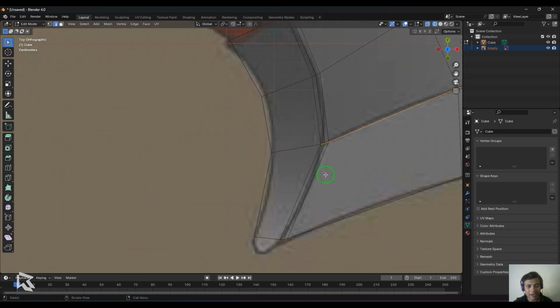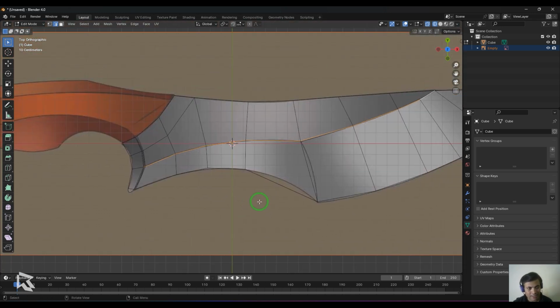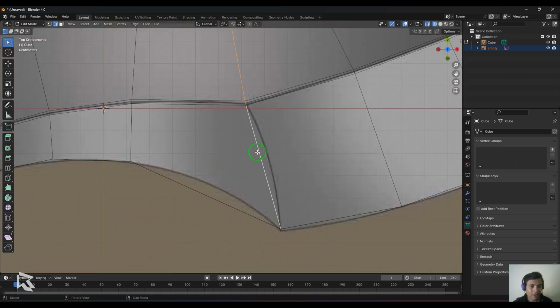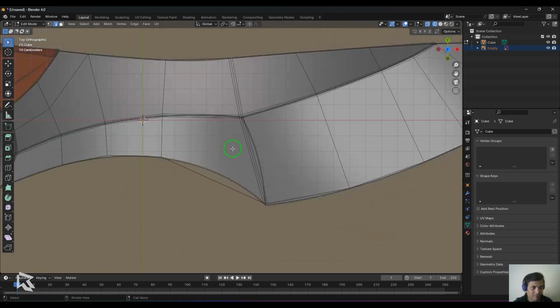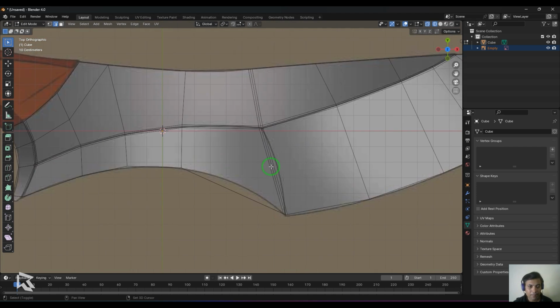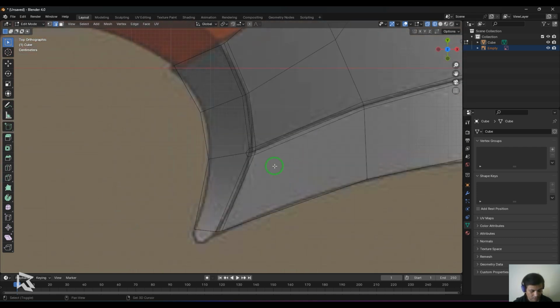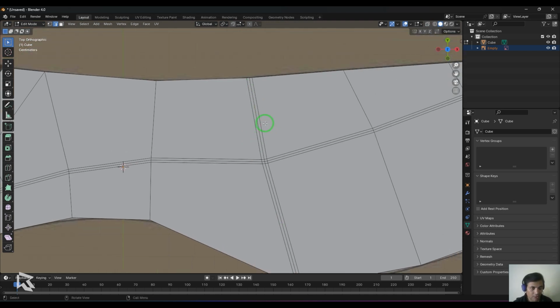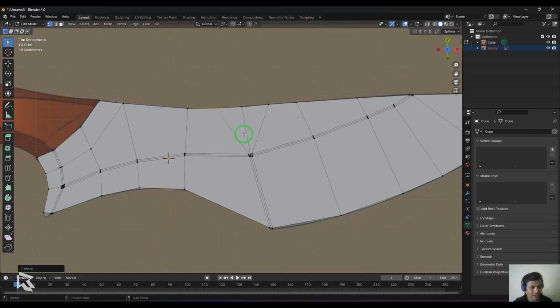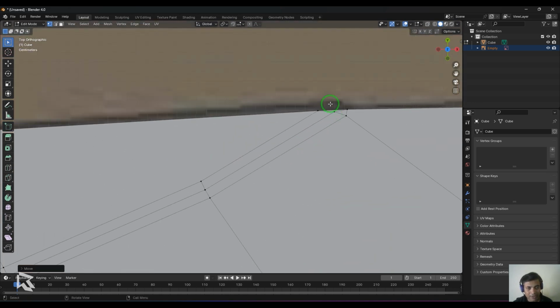This might end up adding some modeling artifacts, but it's okay. Then I start adding 3 lines there again. So Control B and then add those lines there. Anytime I'm adding these lines, like in this case 3 lines, if I stop it here, it may end up giving this kind of mesh, but here I extended it forward. So in that case, I can generally select those points and then start making them dissipate, or just make it loose there, so you don't get that sort of crease lines at those points. If you got any triangles and all, you can start fixing those triangles.